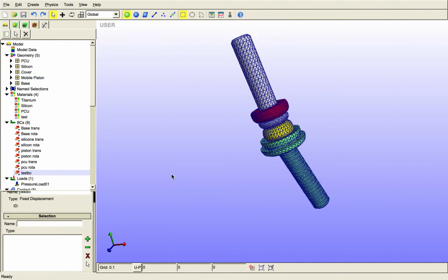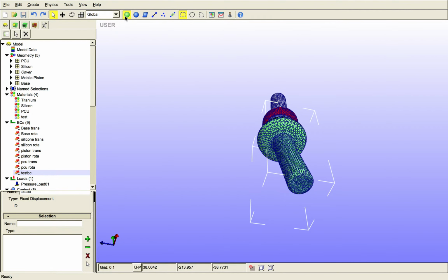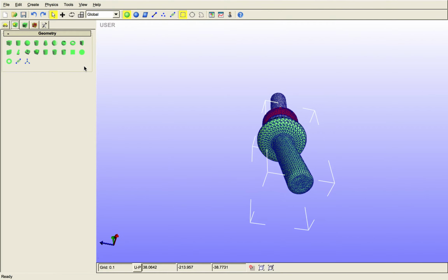This is the tricky part because I didn't know that, but I found out really late. If you want to select element by element, it's really complicated and counterintuitive. So this is the only technique you have. You have to choose the component first. Let's say I want to block a part from the base. So I'm going to select the base because this tool is for selecting objects. So I've selected these objects. Then I'm going to move on to the next window. This window is for producing geometries, as we already have some geometries. We're not going to use it in this tutorial.